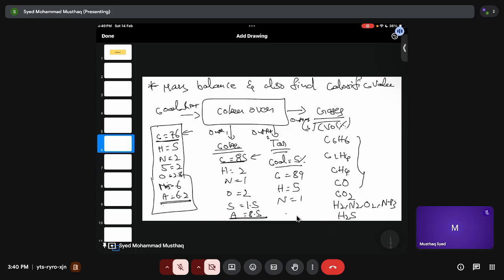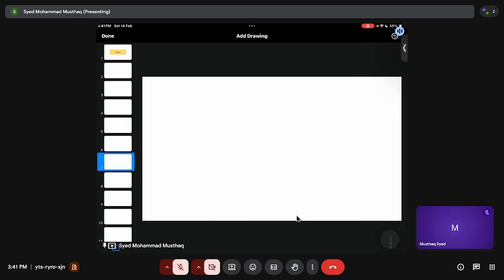So nitrogen, you can see it is involved in four stages, in all the outputs and input. What about sulfur? Sulfur is also involved in two outputs, and there is also the 5% of coal, so you cannot involve sulfur here. Moisture and hydrogen are again a problem. So the only option is you consider ash. It is a simple mass balance, input equals output. There is only one output.